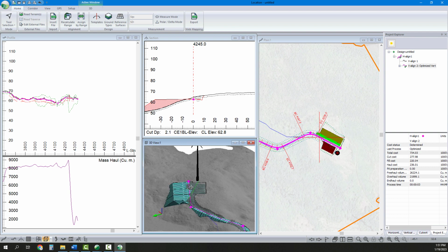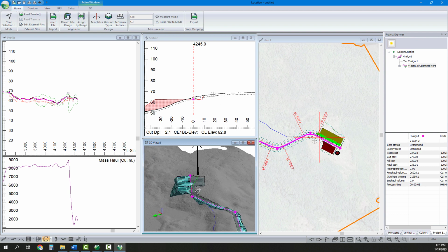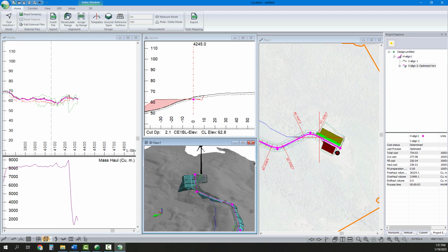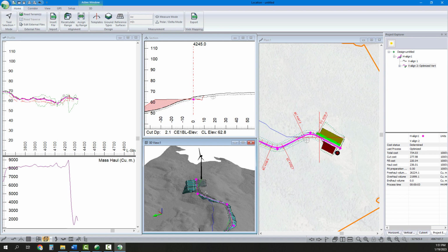it's on solid rock, so we probably don't want to blast if we don't have to. Now what we could do here is we could say, well, let's borrow some material. Just take our superficial material and use that for subgrade here. So sure, let's add in some borrows. Looks reasonable to borrow from there. We could design it if we'd like.